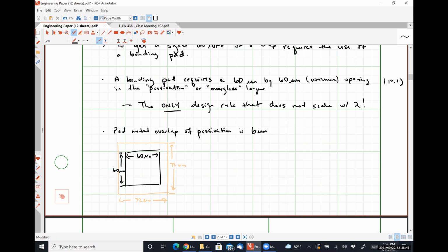A micro manipulator tool is effectively a little box that can move in the X, Y, and Z directions, that steps down mechanical rotation of gears to micron level movements of a needle-like probe, so that you can look at things under the microscope and physically target a specific area on something you're making.